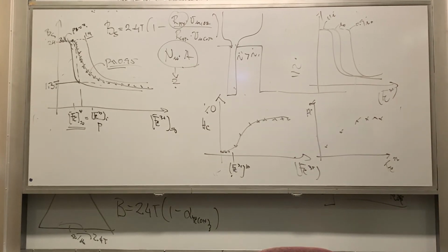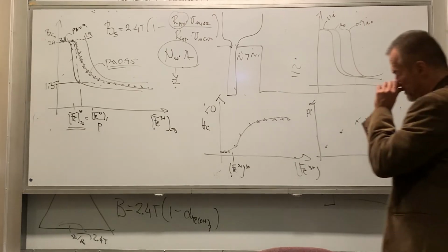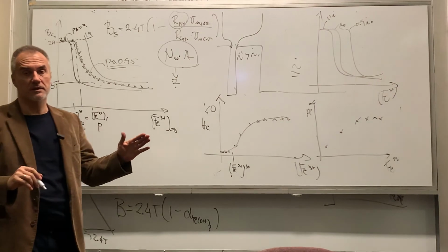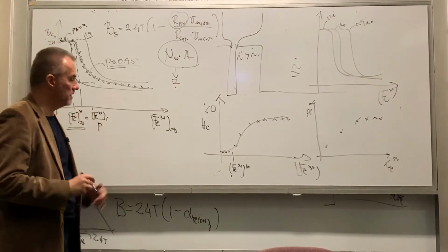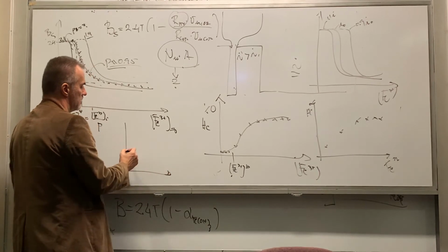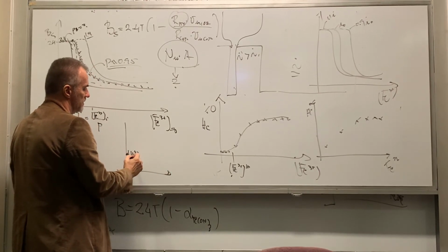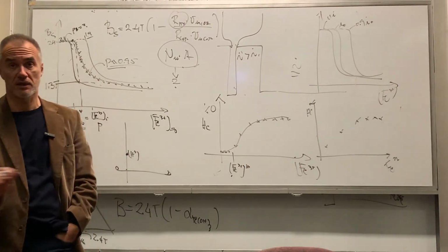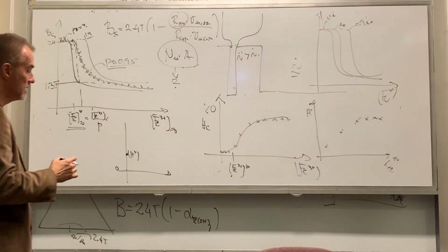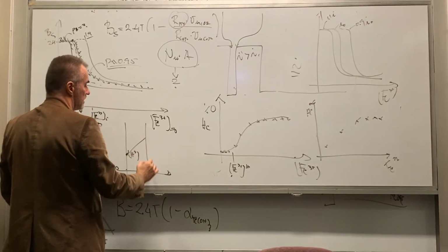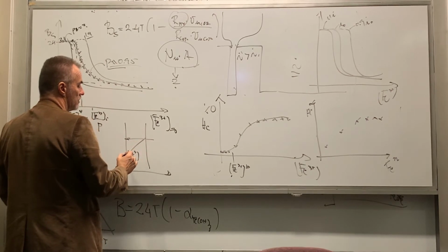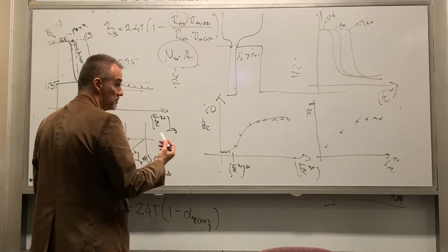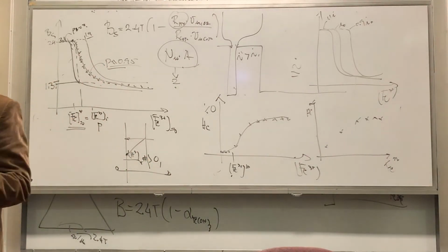there is another thing that I want to tell you is that sometimes when we run this DC deposition process, and we expect to run the process where H plus at the interface never goes down to zero, right? Because if it goes down to zero, you're in trouble, you're going to precipitate any hydroxide, right? So in this particular case, the balance is such when we do electrodeposition that H plus at the interface will be bigger than zero or will be much bigger than zero because otherwise there's no point discussing, right?